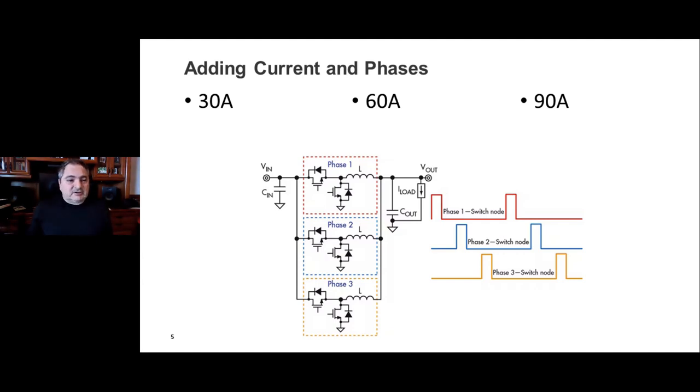So I rounded this up and added some margin. Let's say there's 270 amps peak. We're going to design a PDM for 270 amps continuous or peak. We divide 270 by 30 amps and we get 9 phases. So 9 phases is essentially 9 permutations of power testing that we have to do.